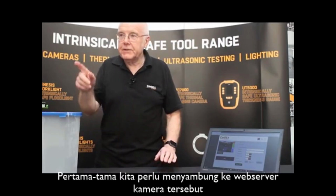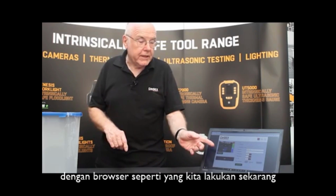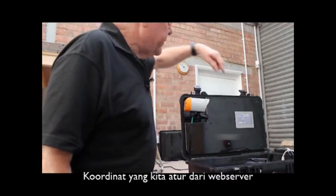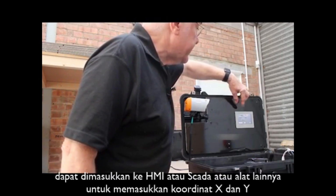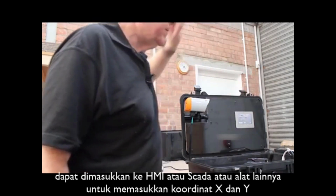Initially, we need to connect to the web server of the camera with a browser like we are doing here, and then we can set up our X and Y coordinates. And then the coordinates you've ascertained from the web server can be inputted into your HMI or SCADA or whatever other device you're using to input the X, Y coordinates.